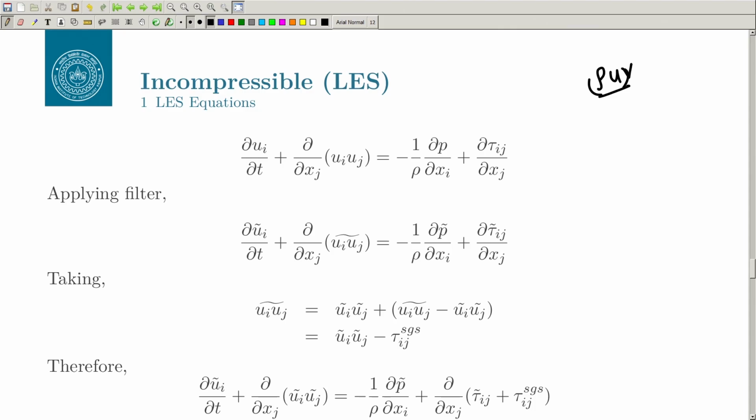If you have rho u v, for example, you get a triple product, and there are many terms which complicate the equation a lot. That is why it is easy to visualize in incompressible flow, where your rho is a constant and u, v are two variables you can easily handle.